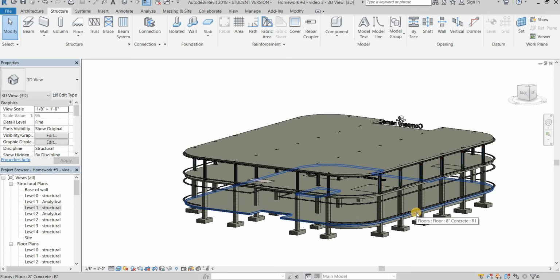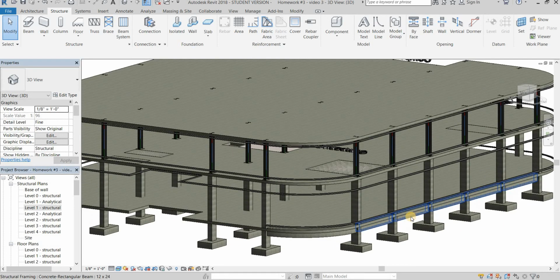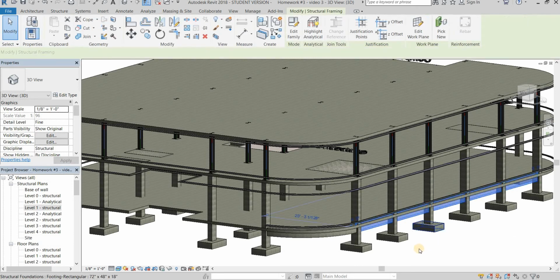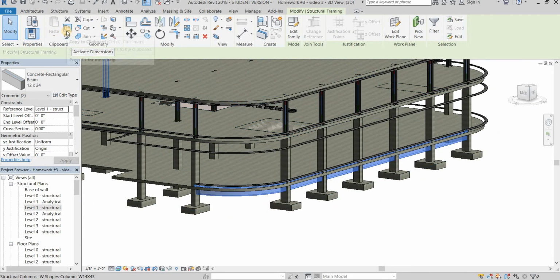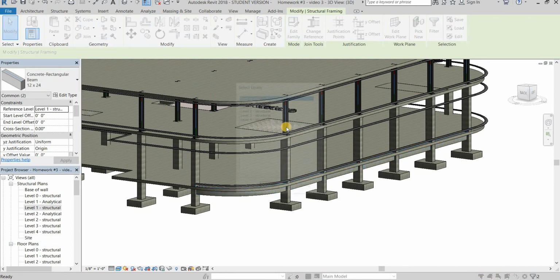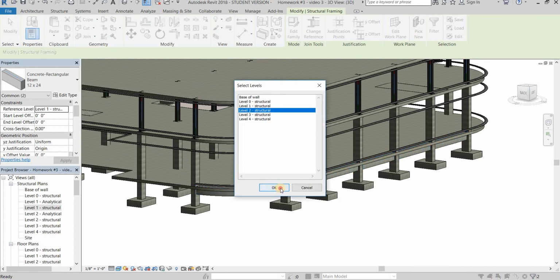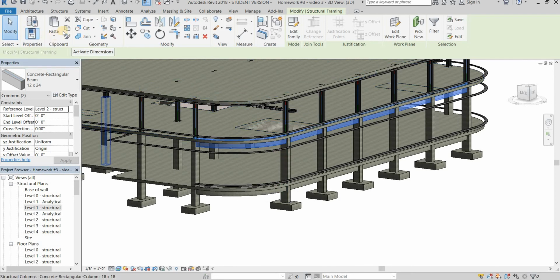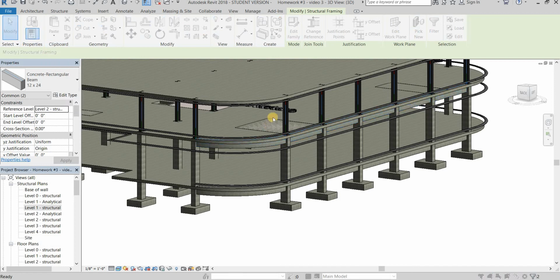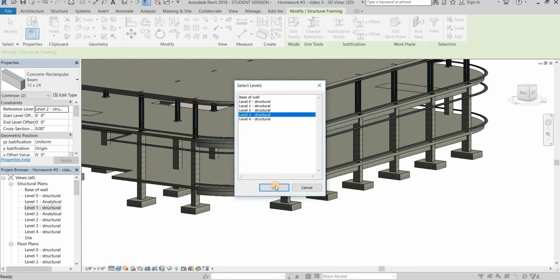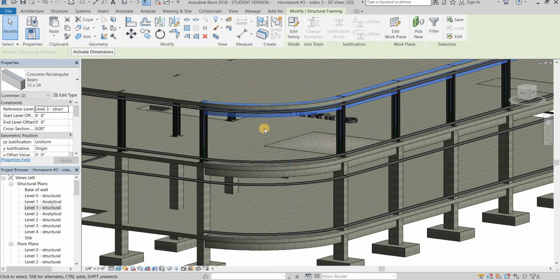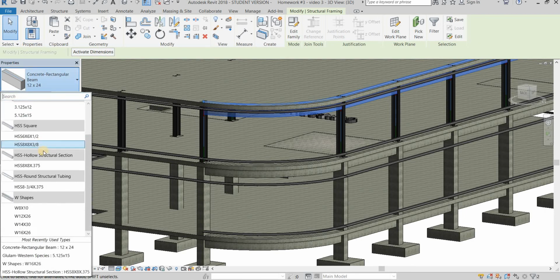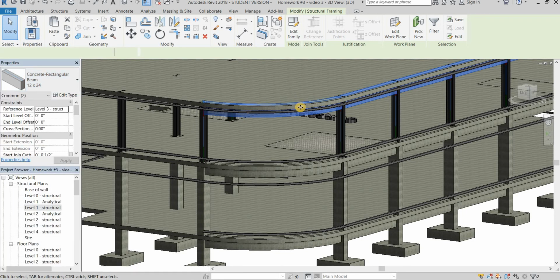So one thing I highly recommend is, instead of doing it floor by floor, you can select one beam, press SA to select all. Okay, so now you will copy to clipboard, paste, align to selected levels, level 2, okay, and it should go here. So you can do the same thing, copy, paste, align selected levels, level 3, okay. Remember that here it quite didn't go, that's okay. Remember that here we have steel beams, okay? So I just changed to steel beams.